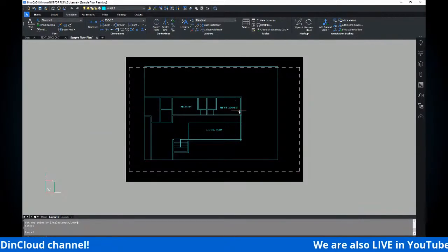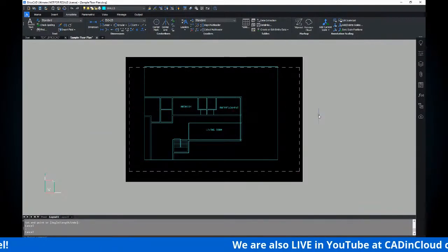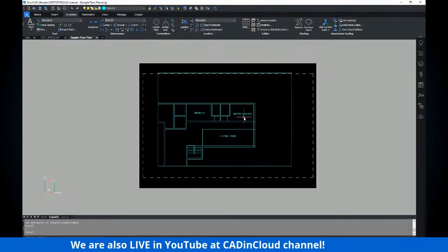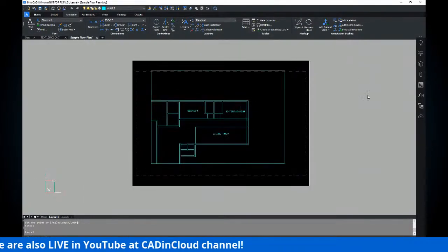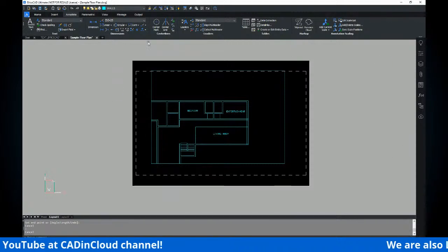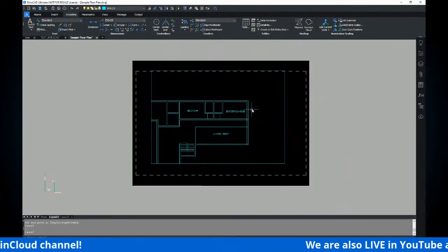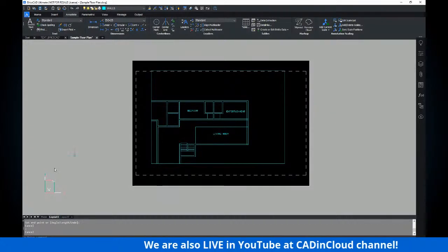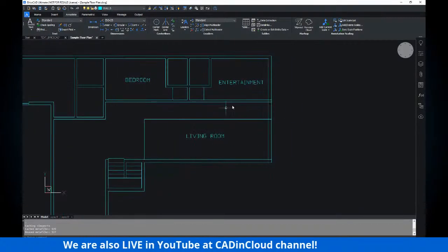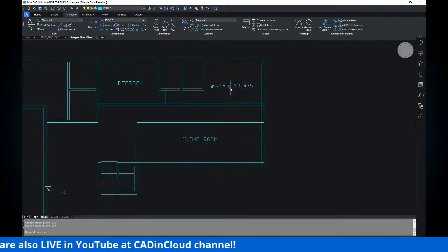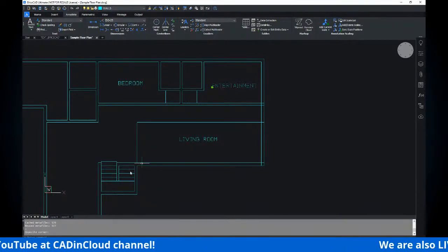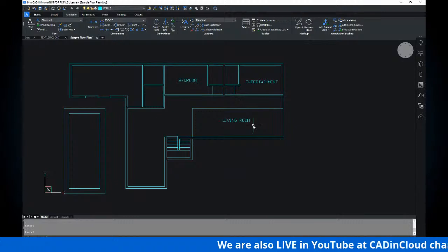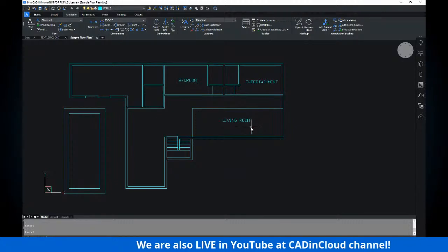It will be exactly 2.5 if you measure using a ruler on the paper that you will print for the floor plan. It's a very simple concept. If you want this text to be printed 2.5 millimeter on actual A3 paper, on the model space you are going to put a height of 250 millimeter. So let's try another measurement of the text height.